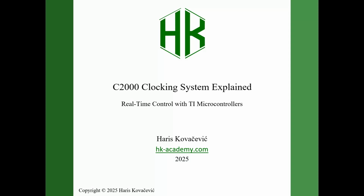In today's video we are going to deep dive into one of the most important building blocks of every microcontroller, the clocking system. I will be using the TI C2000 F280049C as an example to show you both the theory and the practical configuration. In the first part, I will explain the fundamentals, why every MCU needs a clock, what the simplified C2000 clocking structure looks like, how the PLL works, and how the system and peripheral clock dividers are derived. We will also go through a step-by-step frequency calculation example so you understand exactly how your MCU runs internally.